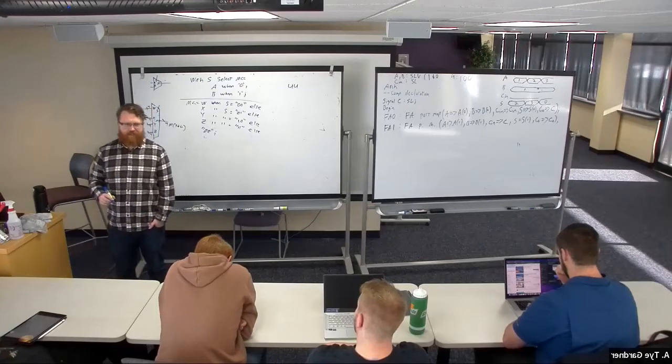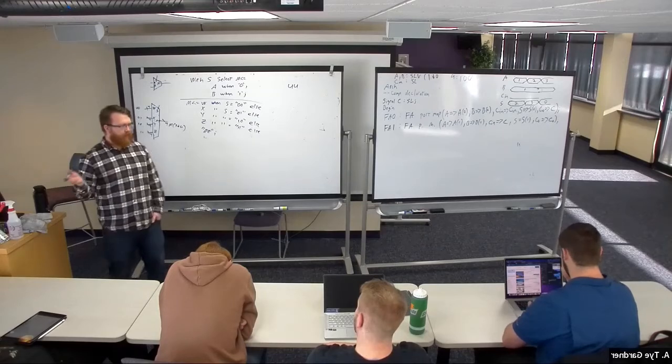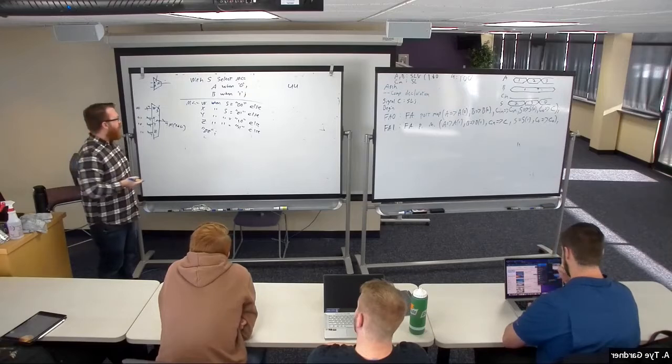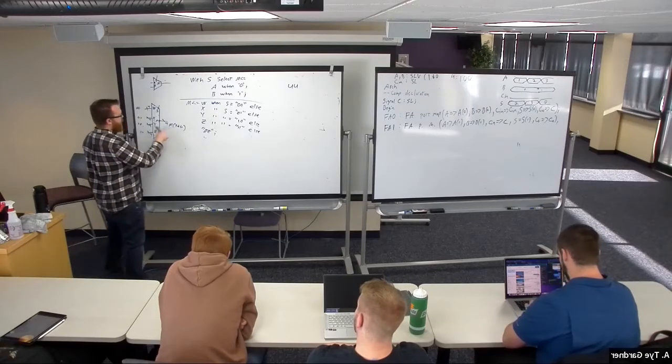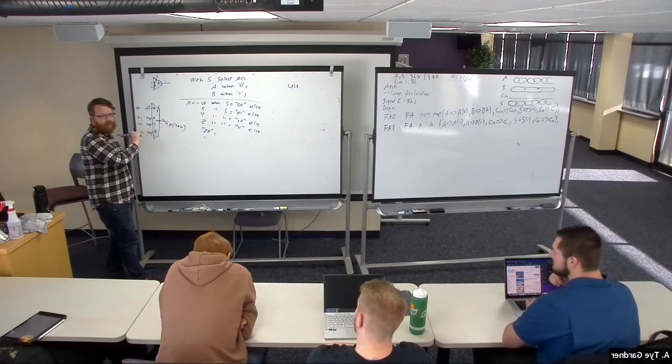You could even do something like Z, right? Z's are high impedance, meaning it turns off. So if you don't select something, it's off, it's disconnected, which is fine. Which you would draw as having an output enabled buffer, right? Which we talked about right before the exam.